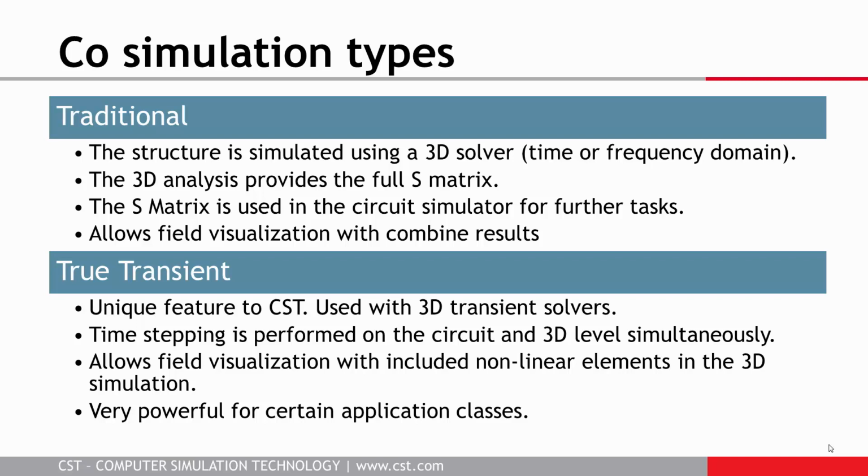In case of resistors, it's of course a little bit boring putting resistors in the 3D model. We have shown that we can do this by lumped elements. But if you would, for example, use SPICE models, we might embed the SPICE models into the time domain 3D model, and this is pretty special. This you could use, for example, to visualize switching behavior, not only in frequency domain, but real time domain switching on a circuit. This is what we call true transient simulation.